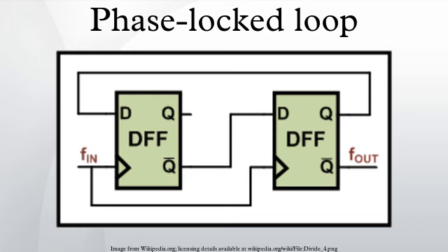Filter. The block commonly called the PLL loop filter generally has two distinct functions. The primary function is to determine loop dynamics, also called stability. This is how the loop responds to disturbances, such as changes in the reference frequency, changes of the feedback divider, or at startup.